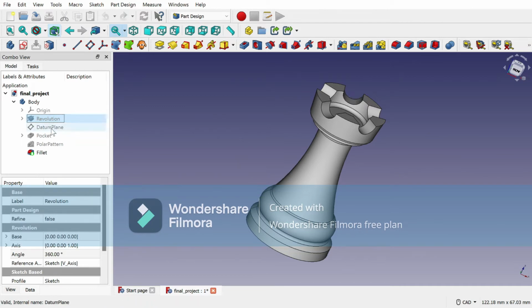So for the grooves I selected the datum plane. First of all I went with the base plane as the datum plane, and then selected the option to revolve it in 90 degrees, and it got transferred to the z-axis. Once it was in the z-axis format, I opted the option to create a sketch.